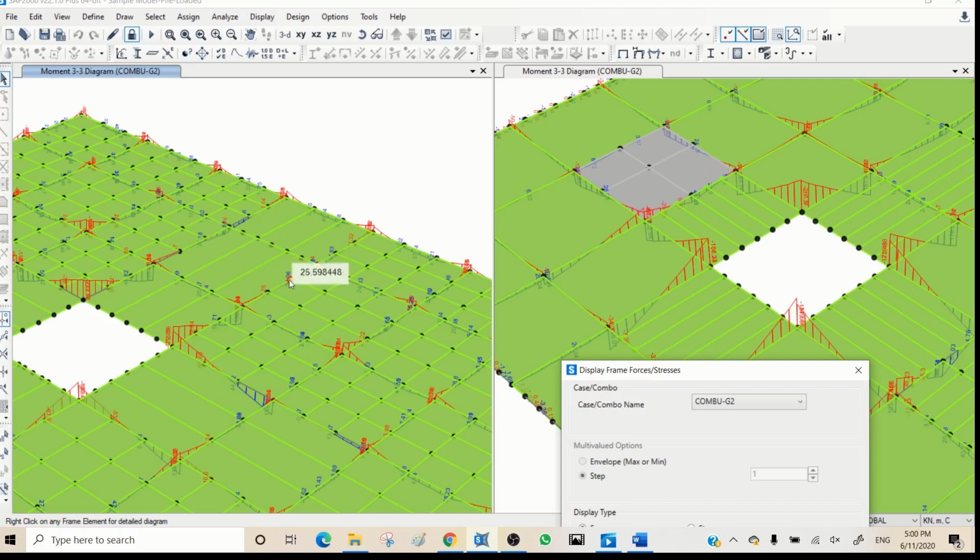So here is a wall, it's not a surprise you don't see anything. The rest you can see the numbers are different. It's back to how the loads will be transferred to those elements. Here we didn't use any automesh, we just subdivided the shell. So you may use automesh as well to make it more accurate.